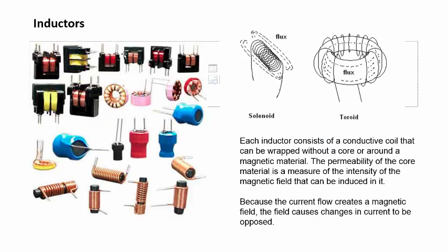So here's a picture of various inductors. As you can see, literally it is wire wound around a core of material. This wire does have an insulation on it. It's often a ceramic material, and many times this wire is called magnet wire. I'll show an example in class, and I'm sorry for my distance student who doesn't get to see all my box of toys that I have. So they are in generally two shapes, a solenoid type shape like this and a toroid shape or donut shape like this with the wire wrapped around it.